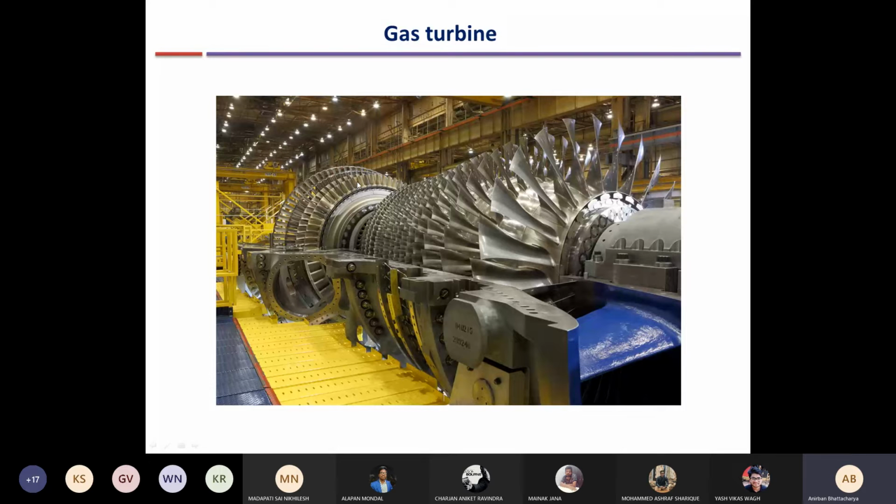So creep is, at a constant stress, elongation with time, right? Because they are undergoing high stresses for a long duration during the flight at high temperature, creep is a very prominent phenomenon. The length of the turbine blades will tend to increase and they will clash with the outer casing, resulting in catastrophic failure of the engine.